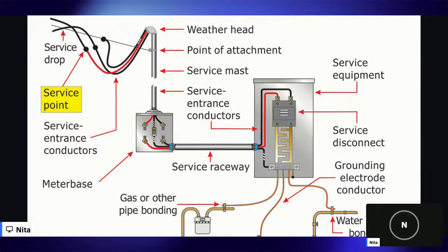After the service point, the wires become what? You mean service entrance conductors? That's correct. After the service point, the wires become service entrance conductors. My cable assembly still consists of what? 2 hots and a neutral. My neutral is serving as what? The return. That's correct.